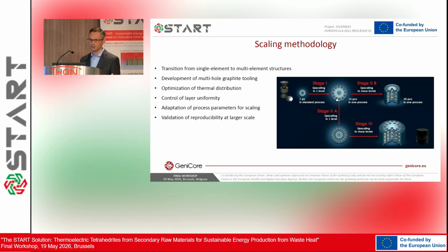Of course, using a bigger system with bigger mass and a higher number of pressing stamps, unfortunately it's necessary to redefine the sintering process, because we have a bigger volume of powder and a bigger mass of the graphite die. But from the first stage, we already know what the load should be, what the heating rate, annealing temperature, and so on should be.